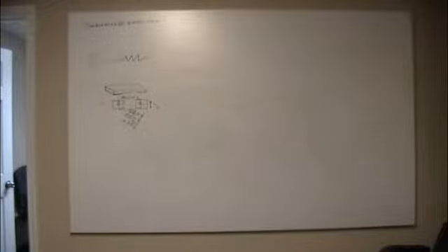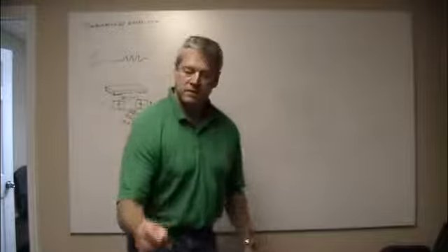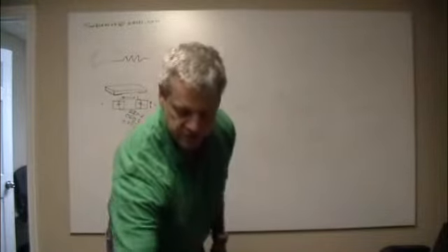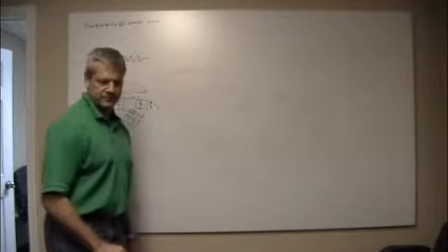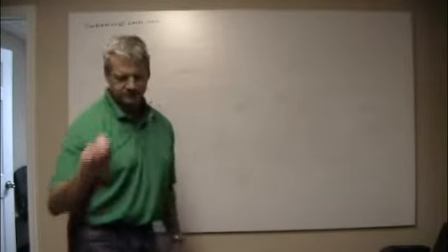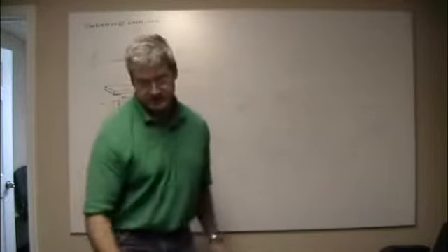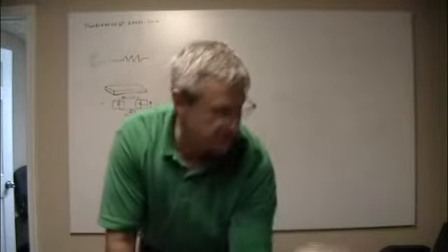I just bent the back legs. That's a standard DIP plastic. That is a 100 mil pitch, so 0.1 inch pitch on the leads. Those are easy to solder by hand. You've seen these, I guess.